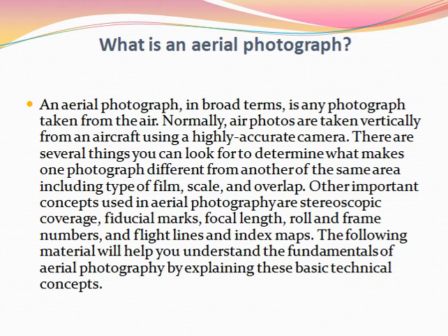Then what are cadastral maps? They are used in the Department of Survey and Land Records, showing location of individual holdings, ponds, roads and streams. They have some physiographic features and contour lines are not available. Map scale is 24 inch is equal to 1 mile to 8 inch is equal to 1 mile, or 4 inch in hilly areas.